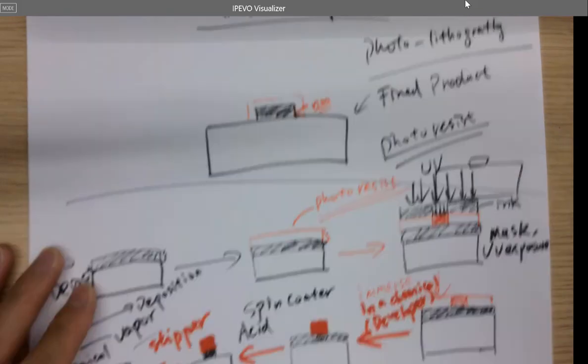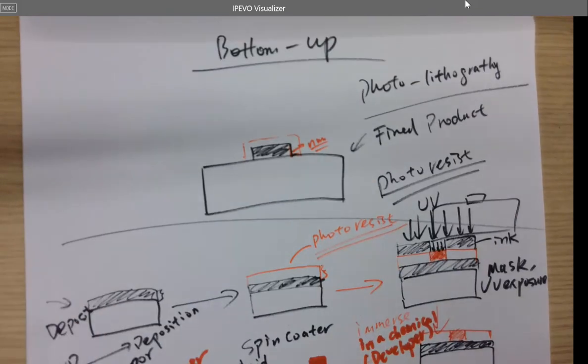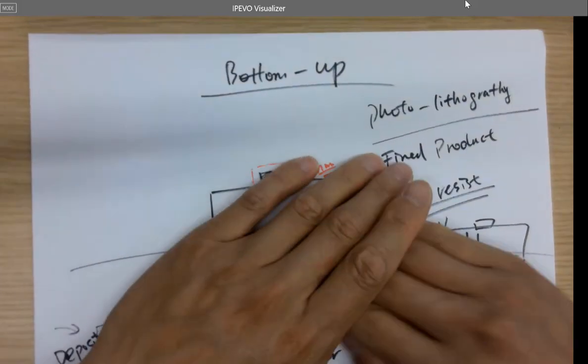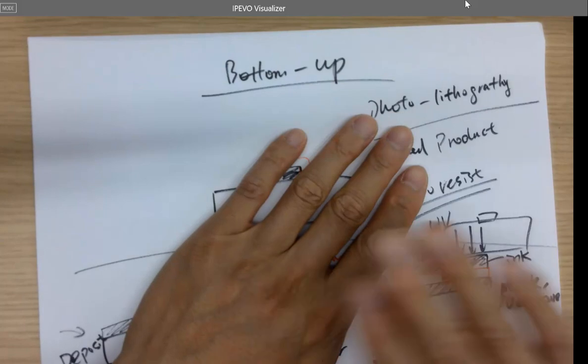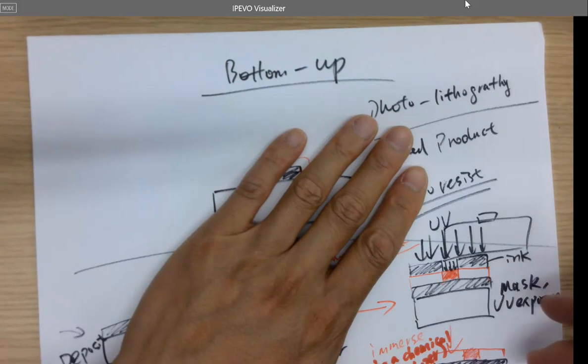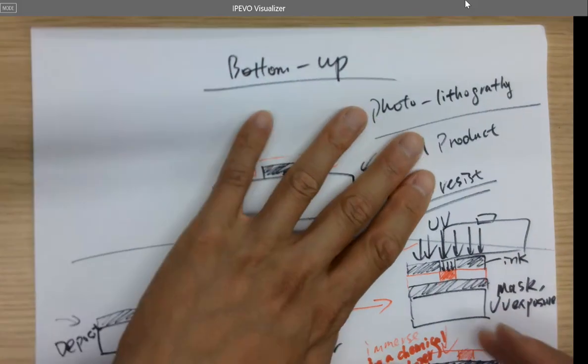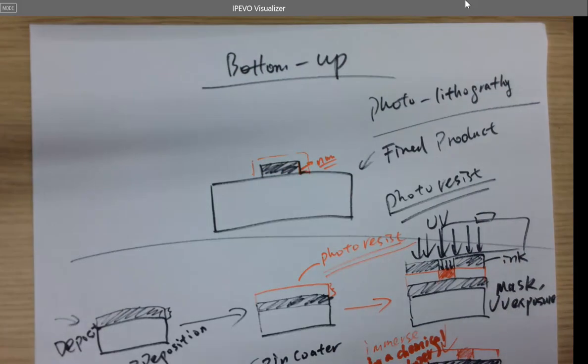And then I put the side of the plastic film which has ink on it onto the copper plate, and then used an iron on the top to heat it up to transfer the traces of ink onto the copper plate. And then I put the copper plate into a solution.